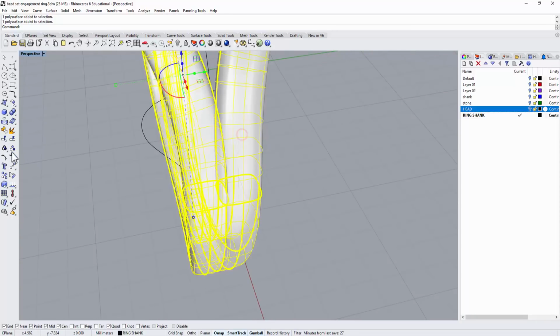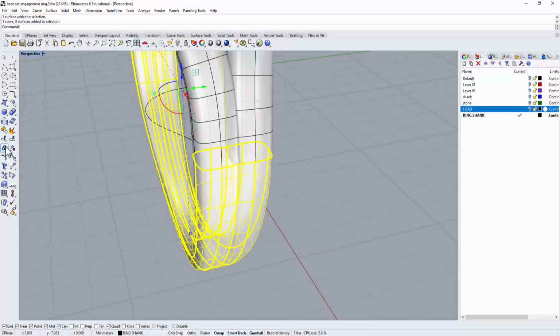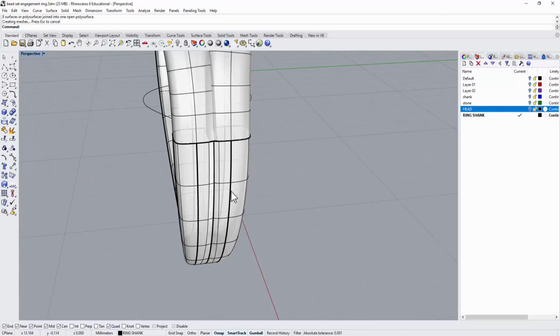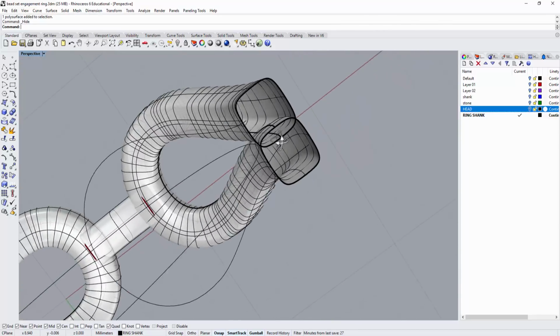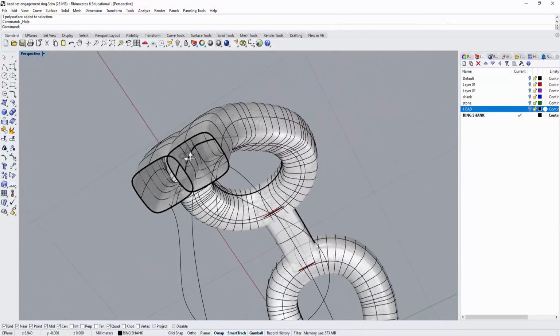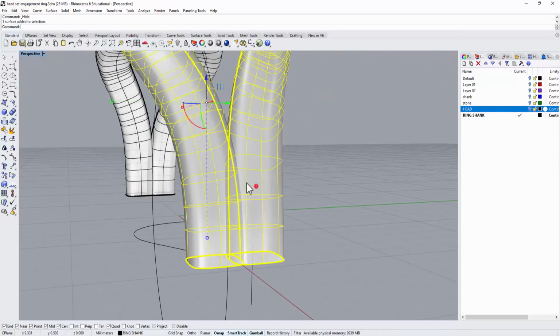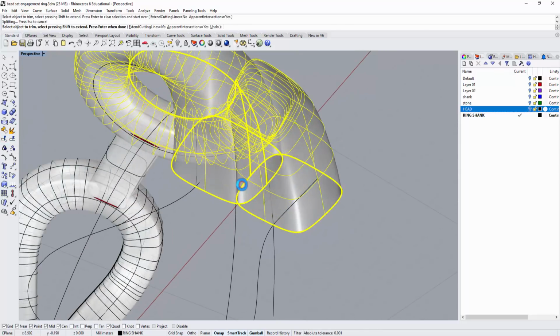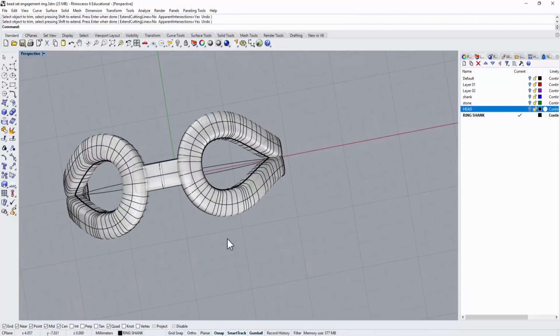If you want to, let's explode it. So back to this part and separately. All the bottom we can join back together. They don't have problem. Okay, so I'm going to hide this one. So you probably will see better what I mean there, because we overlapping the profile a little bit, so you got double surface there, right? If I say I'm going to trim this guy, let's see, I'm gonna trim. It doesn't let you trim, right? So it doesn't work. So the way to do this, you have to split your model first.